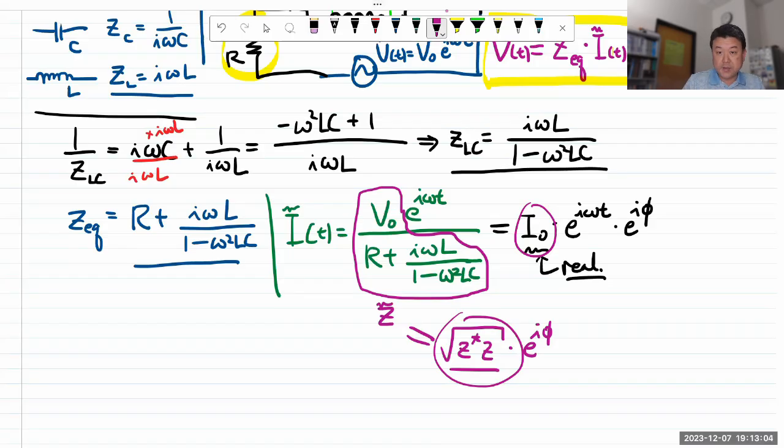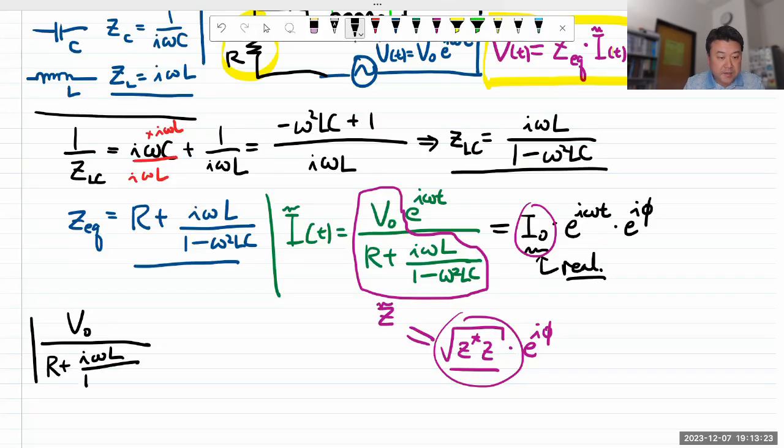So let's calculate that. We are calculating the absolute value of V naught. This is how absolute value is actually defined in complex number algebra. With real numbers, you might have taken the number, squared it, and taken the square root. That's one way to define the algorithm for taking the absolute value. And when you are doing that with a complex number, you do something similar. You just go through an extra step of taking the complex conjugate instead of squaring.